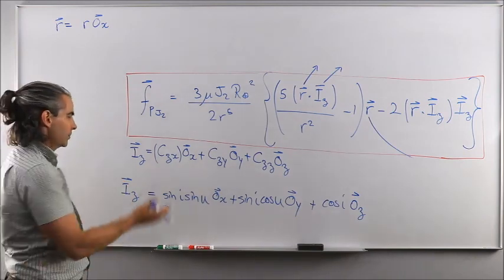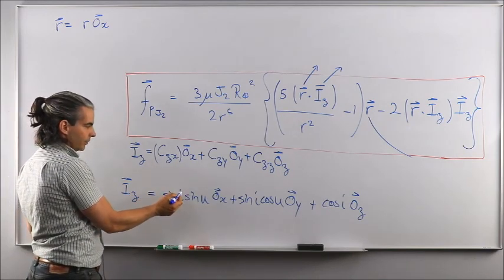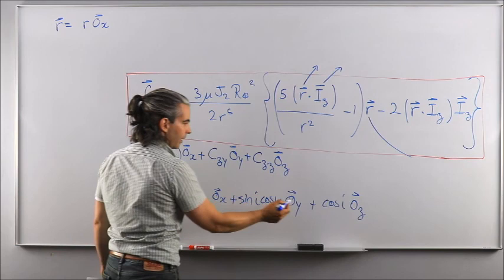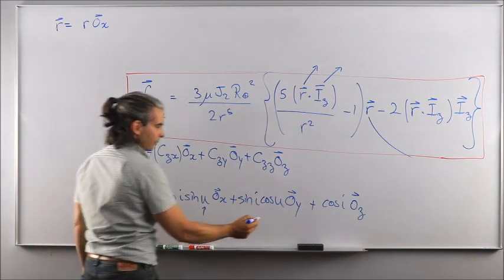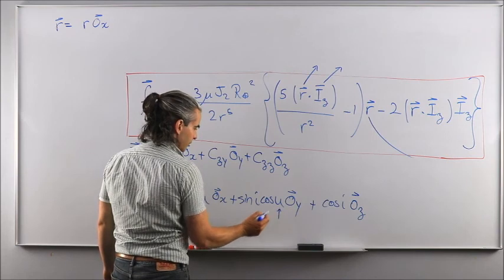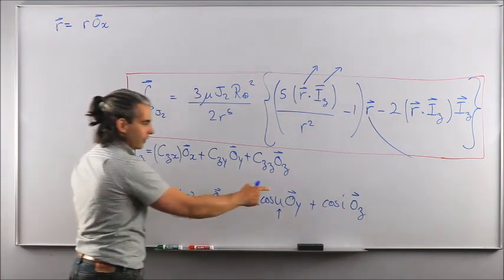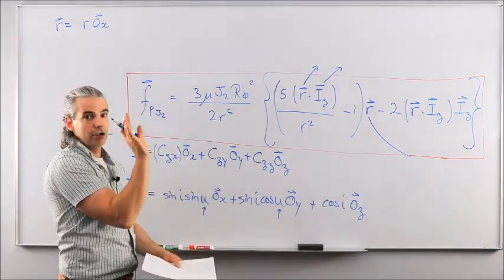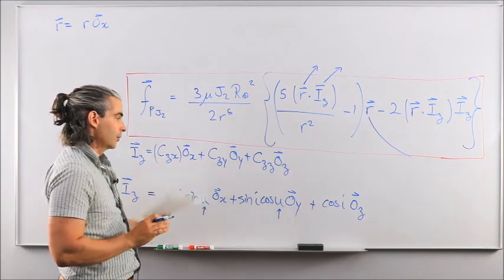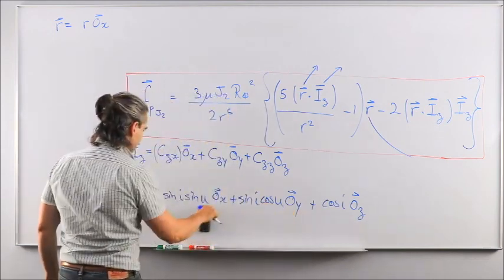Just by looking at it, it makes sense, because based on the inclination of the orbit quantified by I and the current spacecraft position quantified by argument of latitude U, you're going to get a different value for IZ as a function of the orbital reference frame, because the orbital reference frame keeps changing as the spacecraft orbits around. Okay? So that's what you get for IZ.